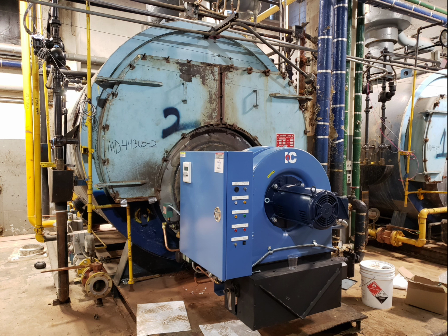By the time 2 minutes within one pass and this thing is just blowing air at a high fire air cycle, you done depleted your pressure. And even by the time the burner finally, or the igniter, the ignition, or the pilot kicks in, you got at least 2 to 4 seconds before you actually get a flame inside, or the burner starts to initiate a main flame. And then when it initiates a main flame, it runs at about low fire for like the first 30 seconds. So throughout this entire time when it's going through this cycle, you have completely depleted your steam pressure.